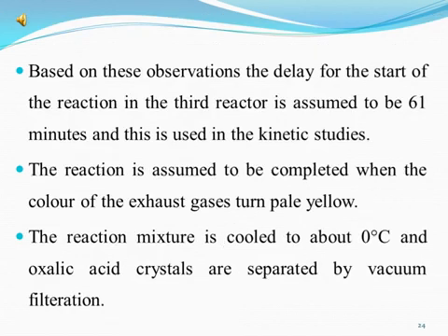As you know, based on these observations, the delay for the start of the reaction in the third reactor is assumed to be 61 minutes, and this is used in the kinetic studies. The reaction is assumed to be completed when the color of the exhaust gases turned pale yellow. The reaction mixture is cooled to about 0 centigrade and oxalic acid crystals are separated by vacuum filtration.